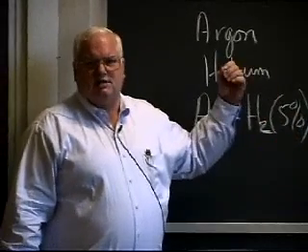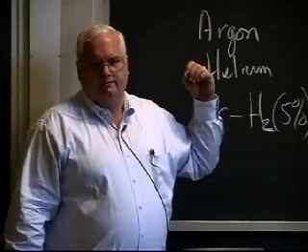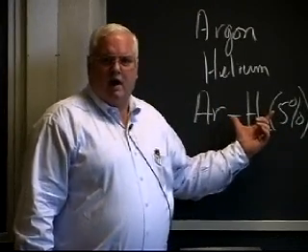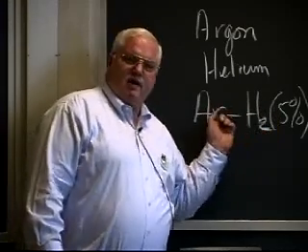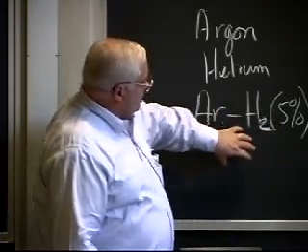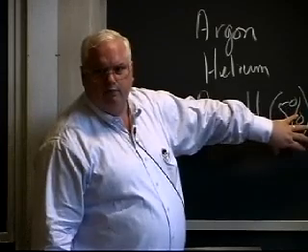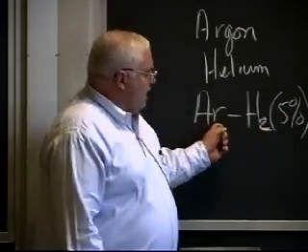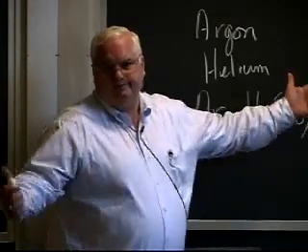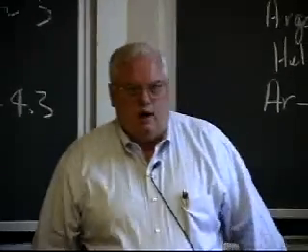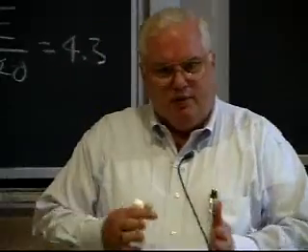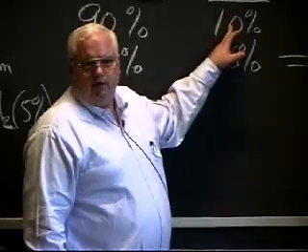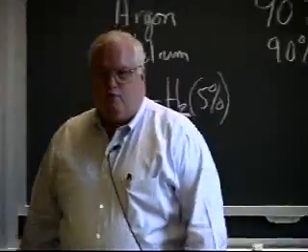But it turns out that's not the major cause. I mean, the thermal conductivity of this average gas mixture only goes up by a 20% improvement. If this is 95% and this other gas is 4.3 times greater, a simple rule of mixture says that I now have 95 plus 5 times 4.3, which is roughly 120%, a 20% improvement in the thermal conductivity. Well, a 20% improvement in the thermal conductivity takes this up to 12%. Big deal. That's not much of an improvement.